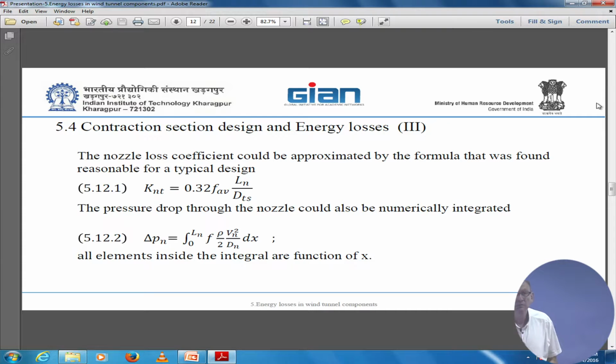How to decide the diameter of the honeycomb? Like the settling chamber, whatever the size, based on that we need to decide how many slots you want to put. You want it as little as you can. The only thing you should pay attention to is how much loss you are going to get for that. But you would prefer to have it smallest. You want only the smallest eddies, vortices, to get through.